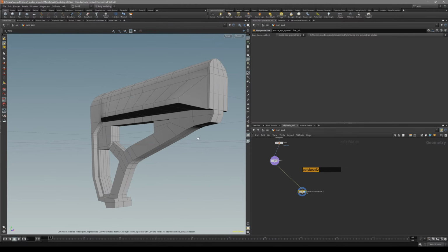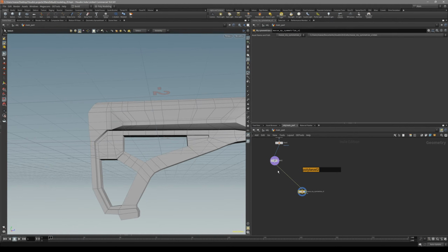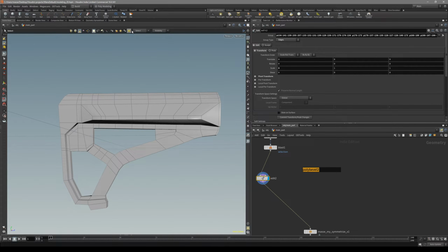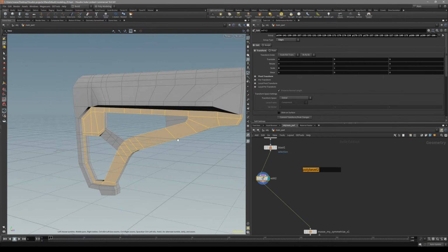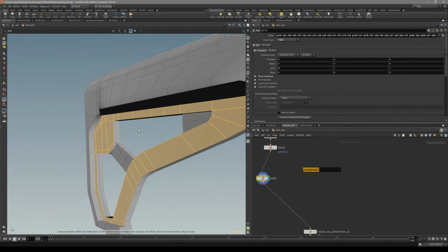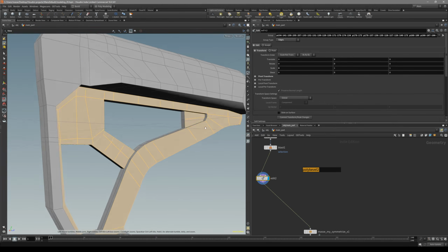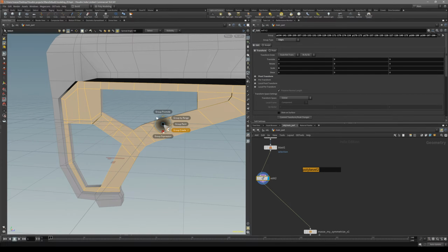Now one thing we can also do is control how thick is this part that we just modeled on the bottom of it. So what I'm going to do is actually create a group. So in polygon selection you can actually go up here and select by normal. You can see it starts to select the chunks of it. By default it's 60 degrees, and this is exactly what I want, basically to create a group that's going to control how thick is this part. And also let's select these also.